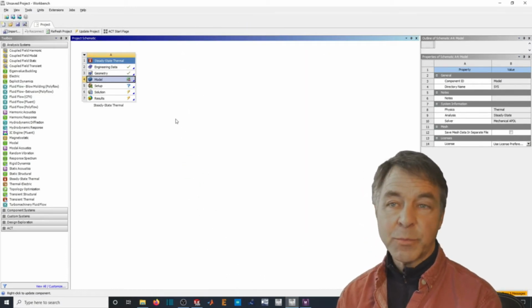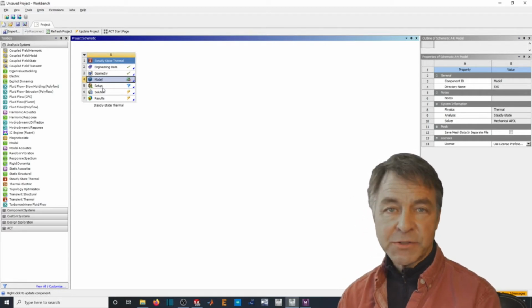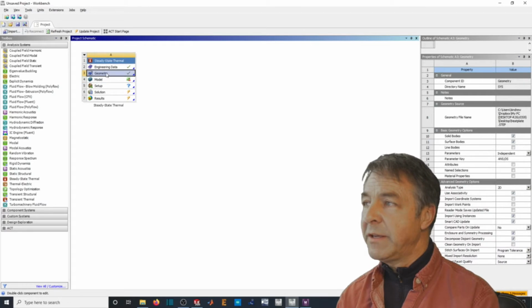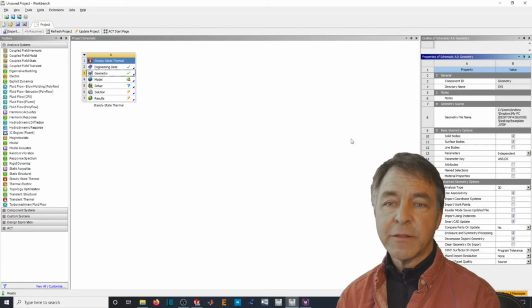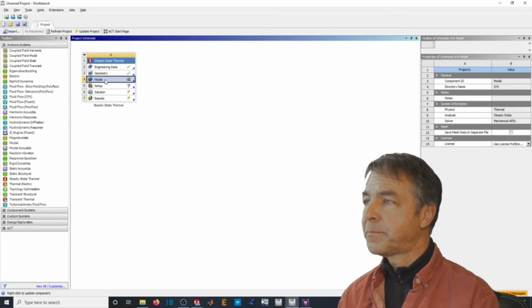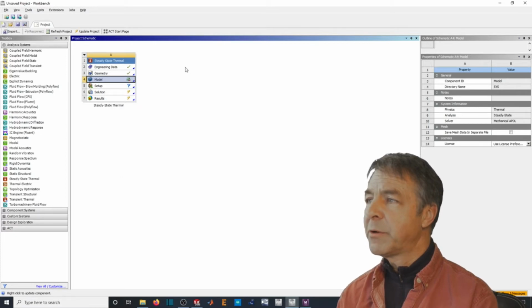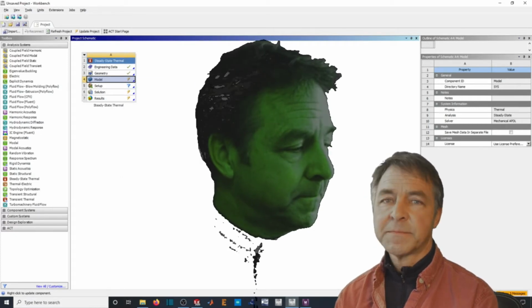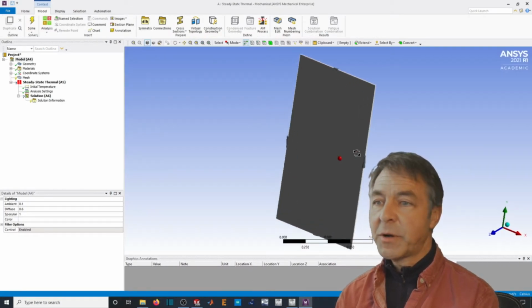And so there we have the problem, which is because SolidWorks saved the step file as a solid, and the 2D geometry was expecting a two-dimensional part, I'm going to have to go back to 3D. And let's try that again. First of all, I'll update upstream components. And there we have the solid part from SolidWorks.